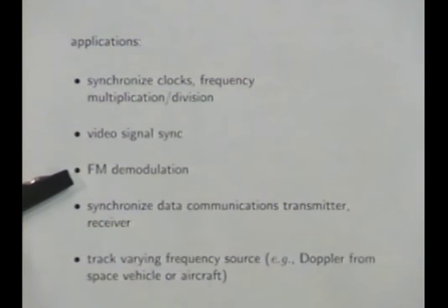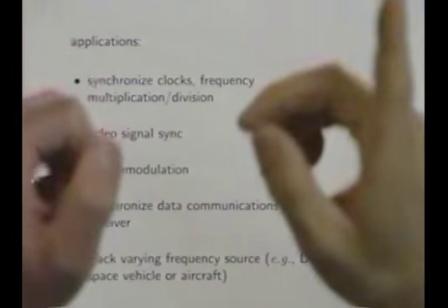It's used in FM demodulation, right? So broadcast FM signals are all around 100 megahertz, but the way the signal is encoded in an ordinary FM signal is by varying that RF frequency a small amount. Anyone know how much? 100 megahertz is the carrier frequency, or 88, or 91 point something, that's megahertz. How much do you think it varies the frequency in an audio when they transmit? Anybody want to take a guess? What is it? Yeah, that's actually very close. It's around 15, 20 kilohertz. It's 15 kilohertz, sort of a maximum one. And then the spacing between channels is 100 kilohertz.